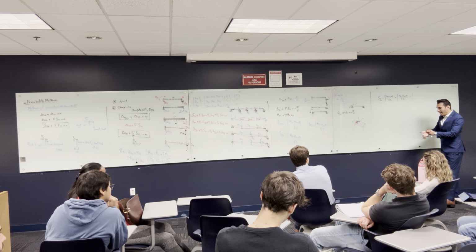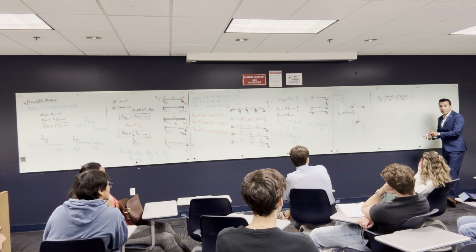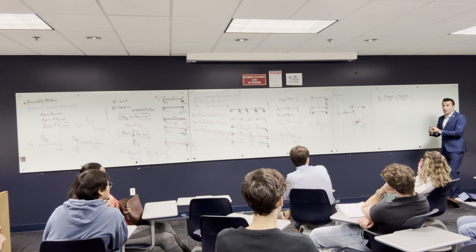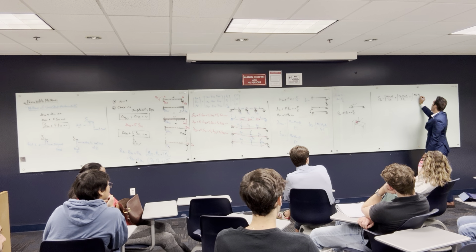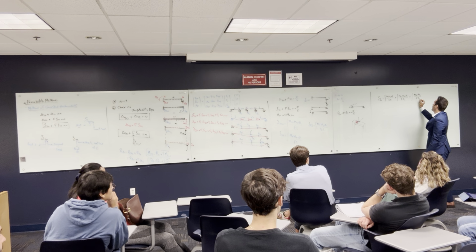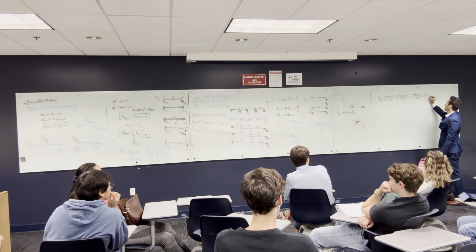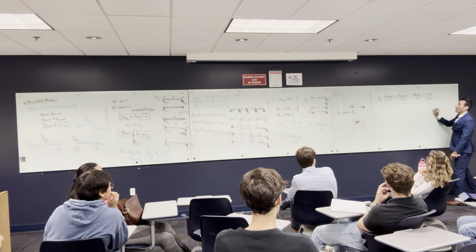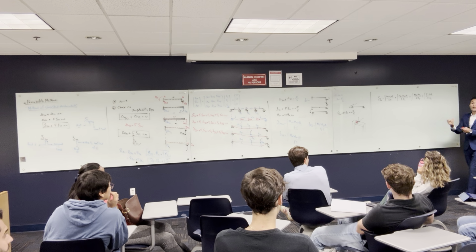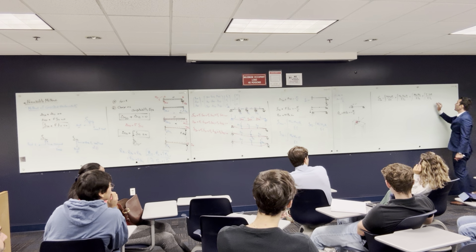And by the way, this is IX, because if the moment is that way, you need the moment of inertia of the cross section about X. If the moment is that way, you need the moment of inertia of the cross section about Y. So you have MY0, MY1 over EIY. If you have a torsion, the torsion is going to be T1, T0, DL over G times IO. So you need to get the polar moment of inertia, which is the resistance of the cross section to torsion.